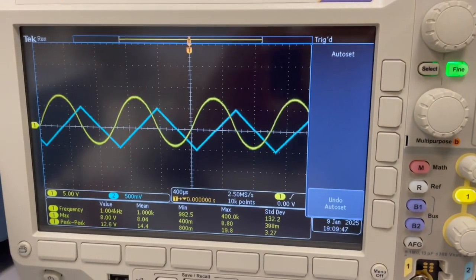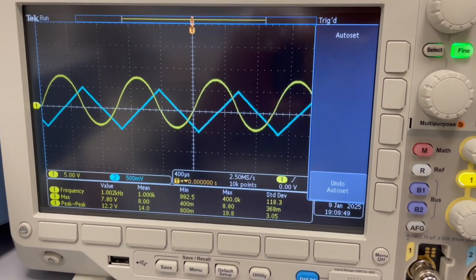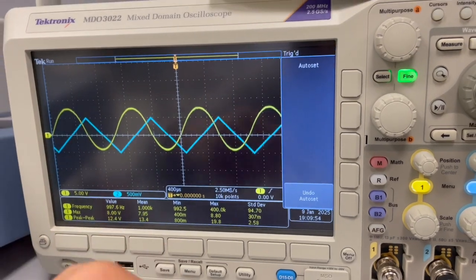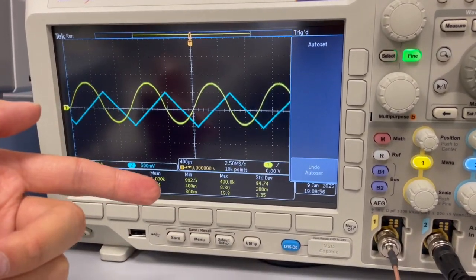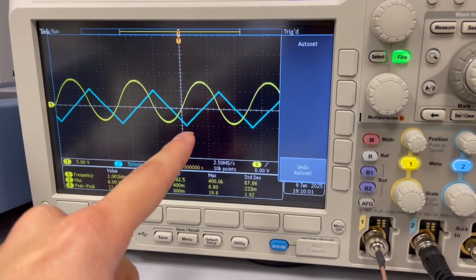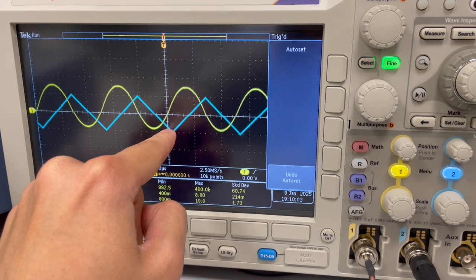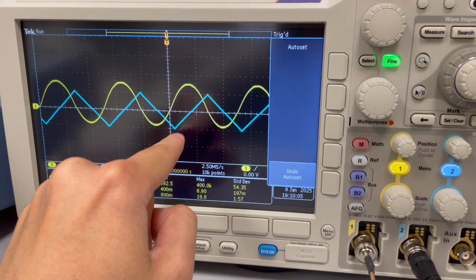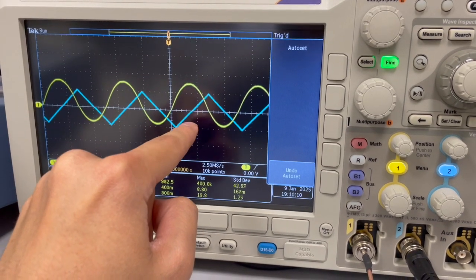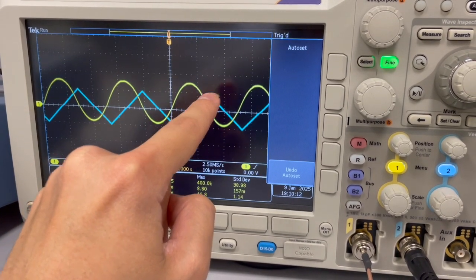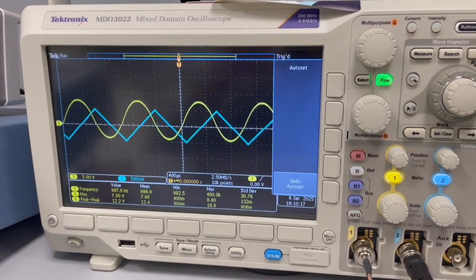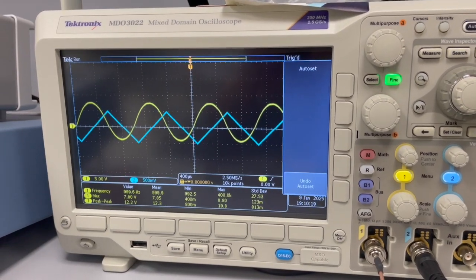The same thing happens if we change the input to a triangle. Now the integration of the triangle function actually gives us a sinusoidal signal, as we can see. In the negative part the area is decreasing, but the output shows that it's increasing. Then once it crosses zero, the area of the output is decreasing. So this is also the same way the integration of the function is happening.